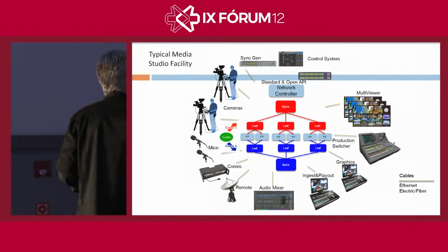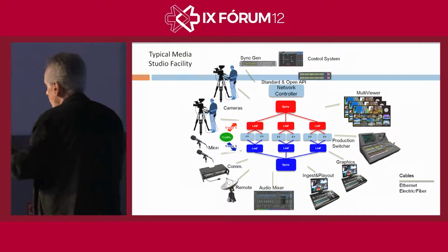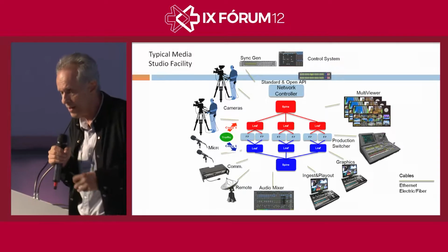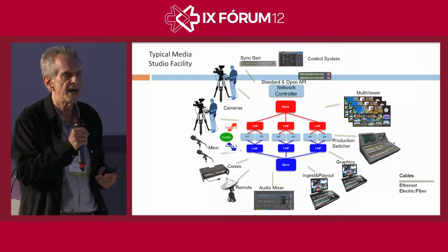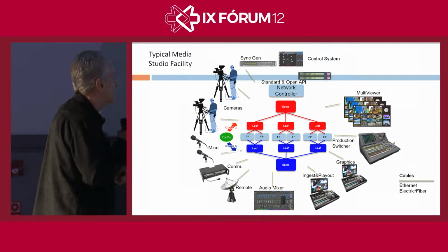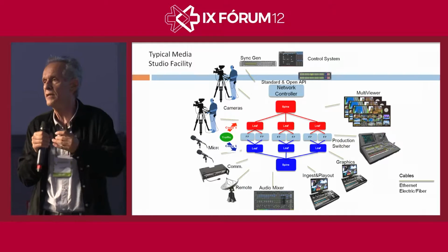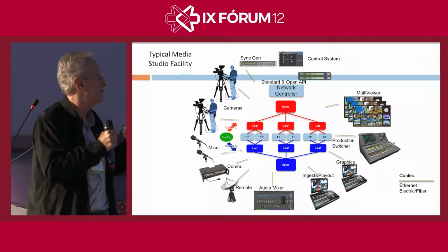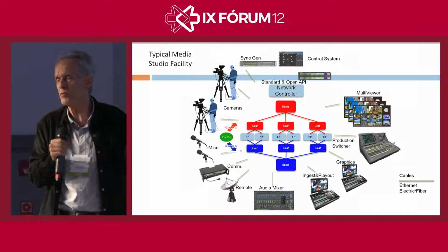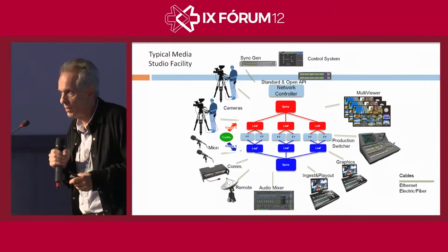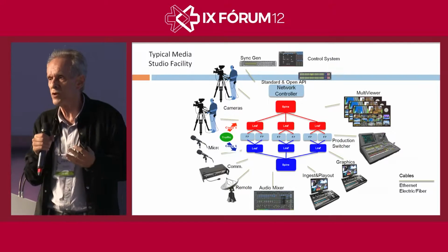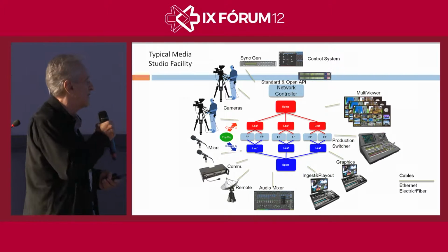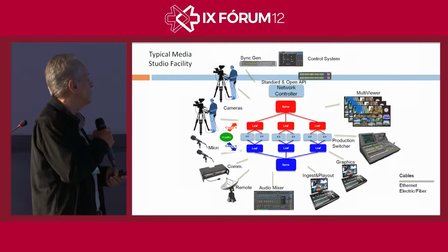and they use two networks here. Everything that is in one network is totally copied to another network. The idea here is not to increase the traffic velocity, but to have the redundancy of this traffic. You will have independent networks, and one can stop. You can work with one network, update it, while the other one is still working, because it would be very difficult to have a live schedule. You cannot stop your network for 10 minutes.